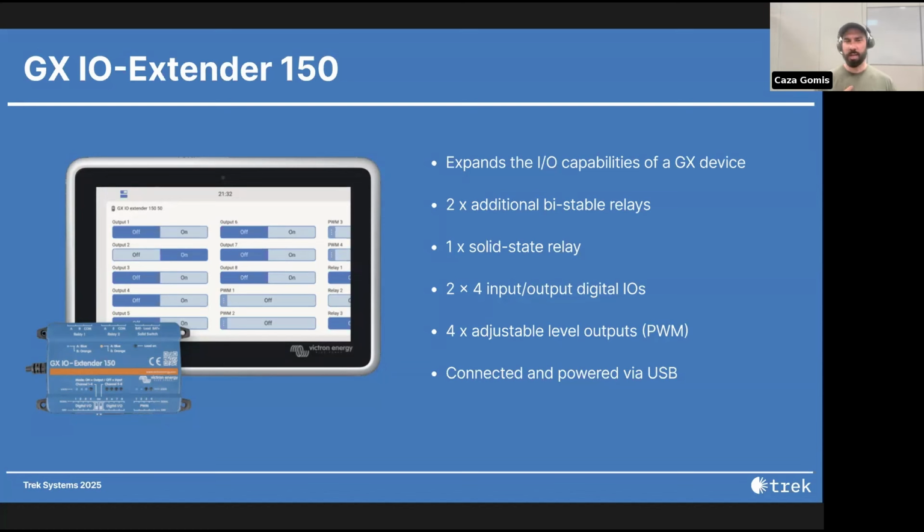But yeah, definitely interesting, and potentially, I don't know if with maybe Node-RED we could turn these relays on the IO extender from a 2-wire to a 3-wire possibly, but then there's still this idea of not having all of the advanced programming capability that lives on the GX device when using the native relay for auto gen start stop. Mm-hmm. So hypothetically, you could do it manually using this, but any automatic start stop settings would just need to be done through the Cerbo itself.